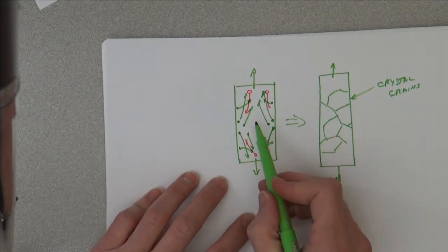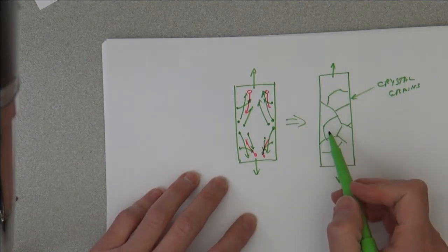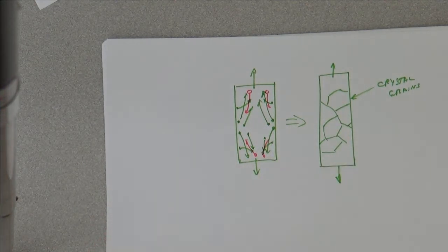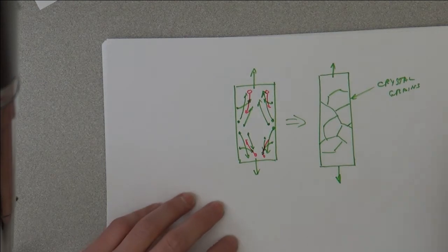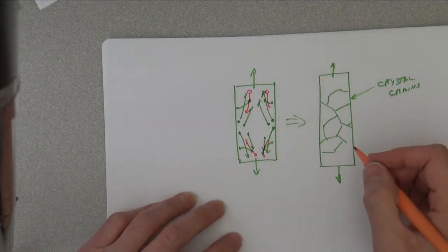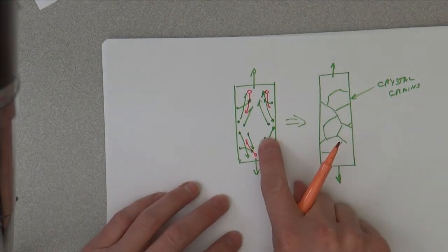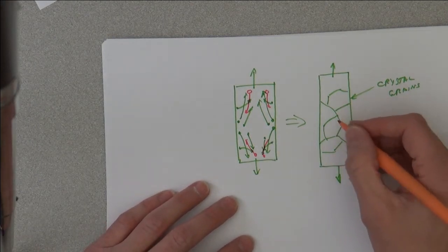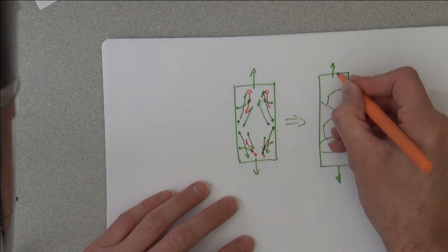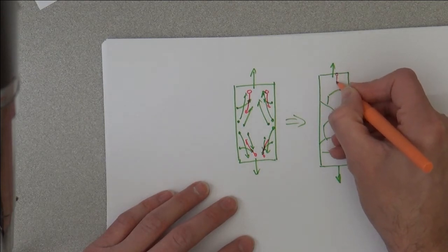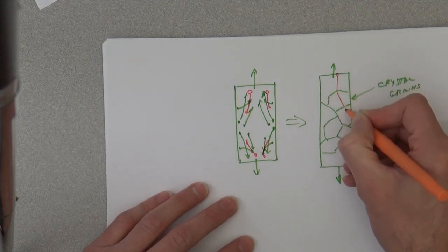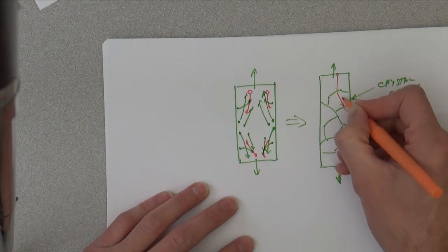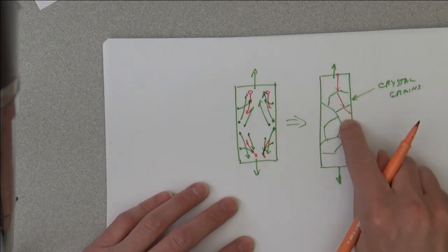So this diffusion process has to be happening within the microstructure, and that's important because when you think about designing materials, you're actually thinking about designing a microstructure. So one way that you can think about the diffusion process is that you can think of it as vacancies that come through and they diffuse through the grain.